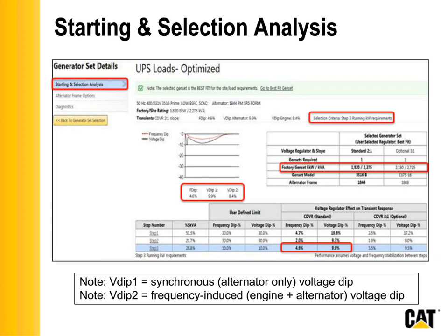And it's important to understand your voltage dip, because voltage dip has to do with quality power. If you have excessive voltage dip, it's not like frequency dip where you stall your genset. Excessive voltage dip affects quality power: your lights will dim, you'll trip circuit breakers. When you're thinking about voltage dip, I talked about how SpecSizer is a full actual transient response tool. Well, if we didn't actually test our gensets in the factory, we wouldn't have that VDIP2 component.